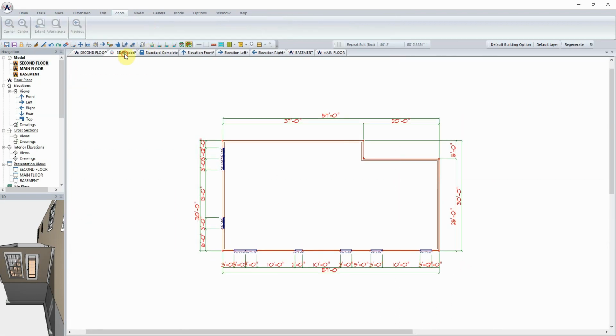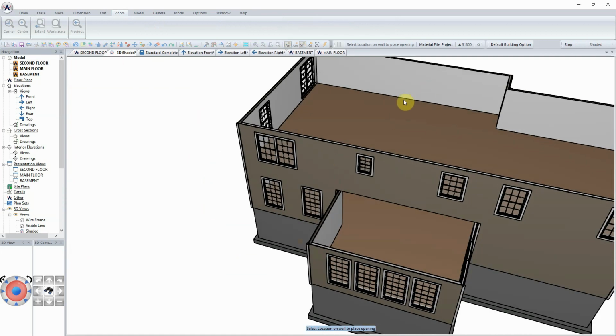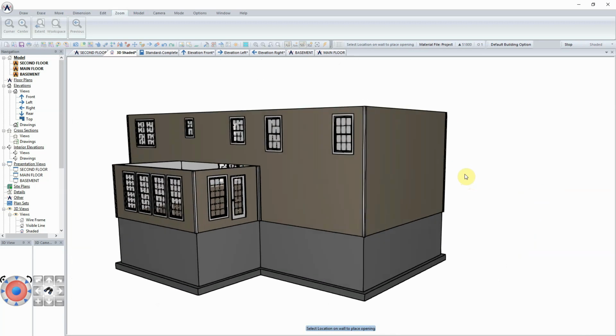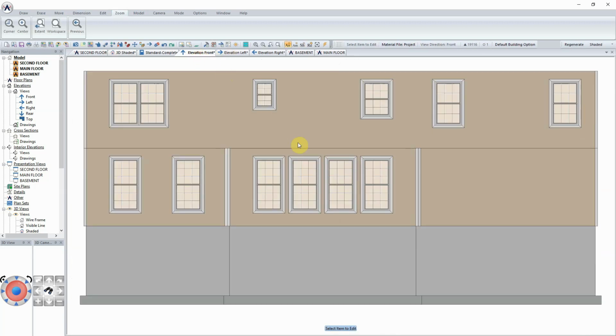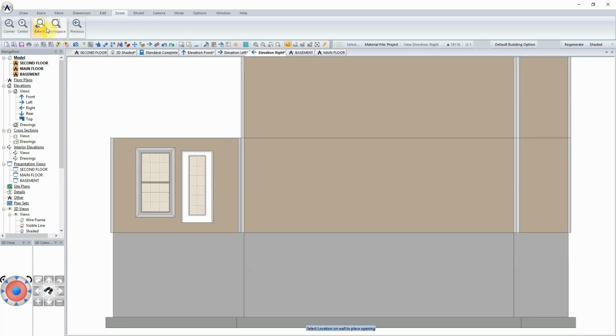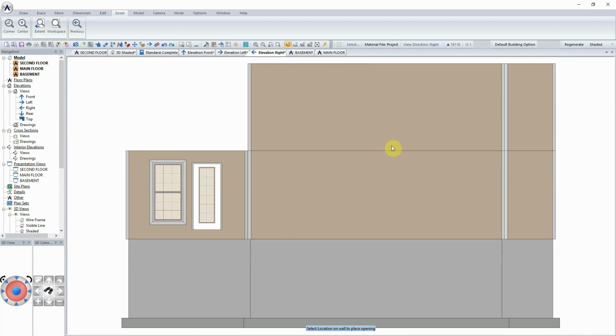And so again, as I look at this inside 3D Shaded, I now have a subfloor in here, I have my wall types in there. If I look at it from an elevation, things are beginning to snap into shape, and I'm just going to continue to keep these zoomed to extent so I can see everything as we work with it. With that in place, walls, structural floor systems, we can now take a look at putting the roofs on.